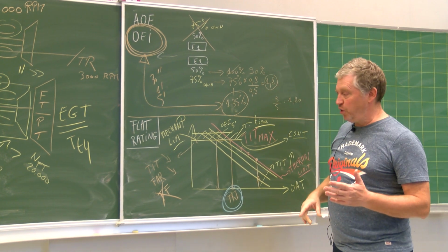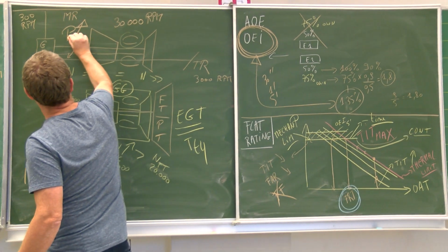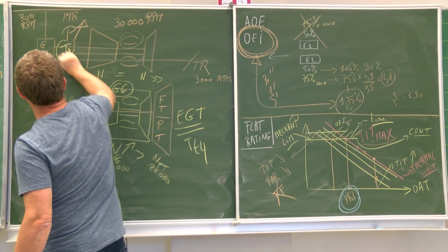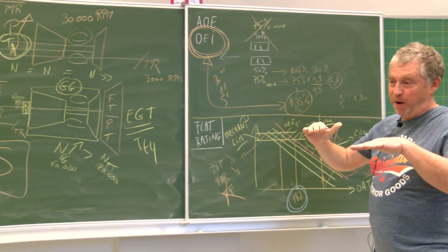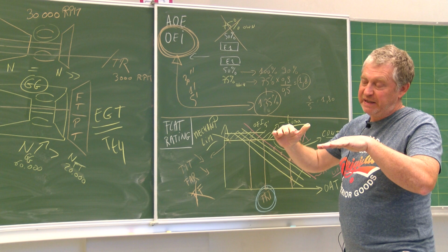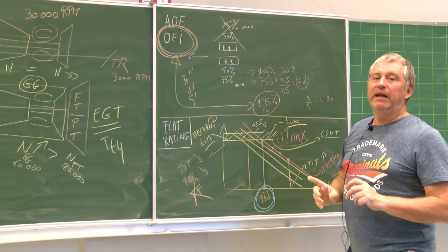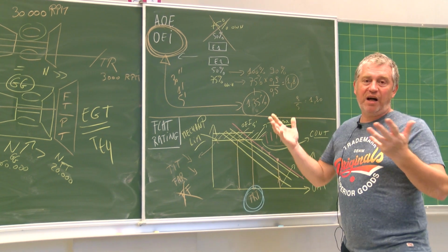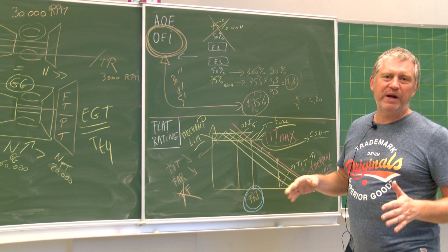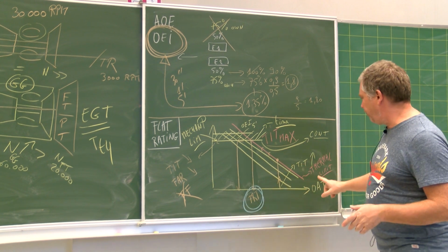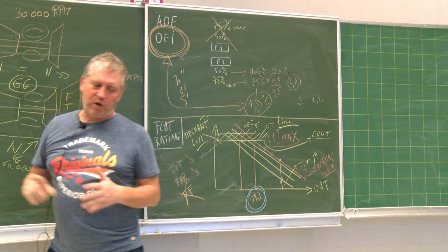And you have also an indication of the torque. So not of the power, but of the torque that you have here. And you will see also, because the power is increasing and rotational speed is constant, the torque increasing. If you take off, let's say, with just the pilot, you will not have reached any of the EGT limit and any of the torque limit.